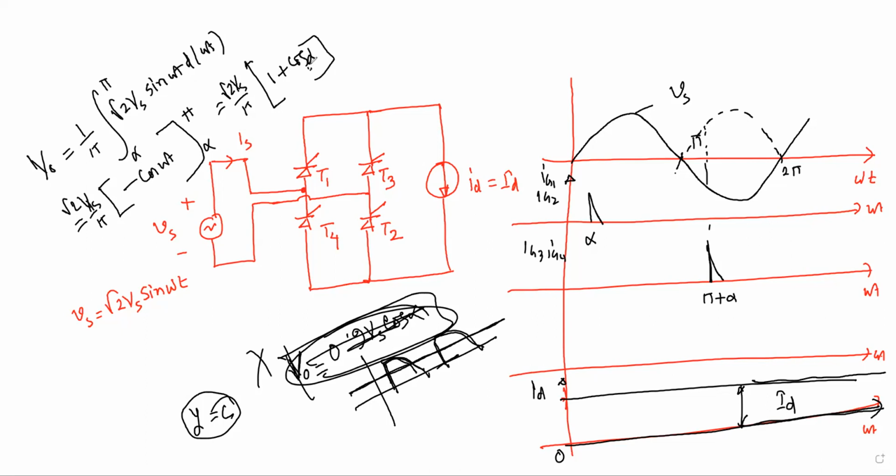So the question is that we are actually changing the DC voltage, like for a DC motor or any DC load. If you want to change the speed of the motor or anything, the DC load, you can use this kind of rectifier. Actually, we use this kind of rectifier and connect it to an inverter. Then we change this DC voltage, and the inverter voltage will be automatically changed. Then that inverter output is AC, and that AC can be used for, say, AC motor control or AC load, light dimmer, even you can use that.